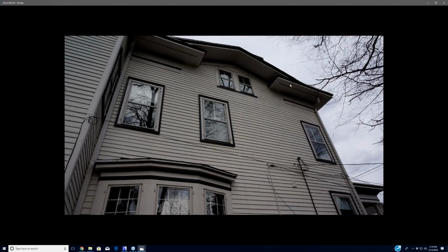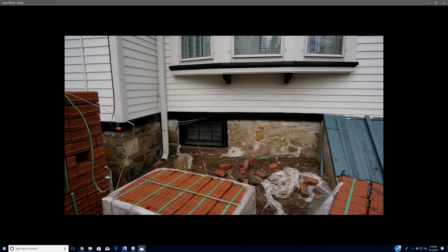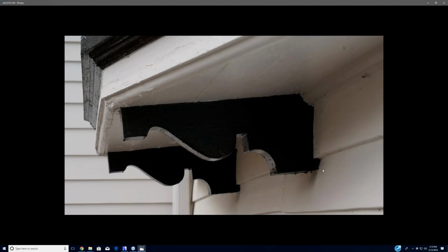And then this is where the camera really comes into play: how big are these rakes? Where do the rakes terminate? Are they consistently that same detail? This type of stuff, I'll measure the overall. I'll measure this dimension in 2 dimensions on the floor plan. I'll draw that, create a slab, turn it into a morph, rotate it, and now I have these 2 brackets.